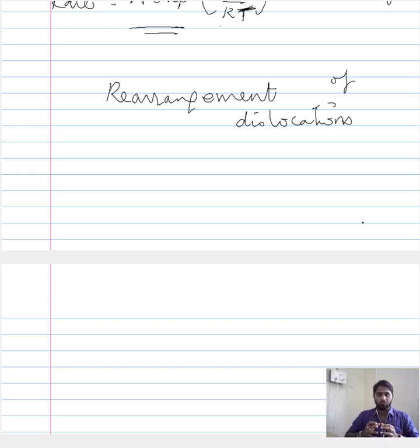This is also one of the ways that annealing establishes its purpose. Annealing wants to reduce the energy of the system, and this is also achieved by rearranging the dislocations. Now let us see what this rearranging means. Let's stick to this simple edge dislocation. When we talk about an edge dislocation, something like this, you have an extra row of atoms in this region, and that causes a compressive strain, or let's talk in terms of stress. It causes a compressive stress because you have an extra row of atoms.